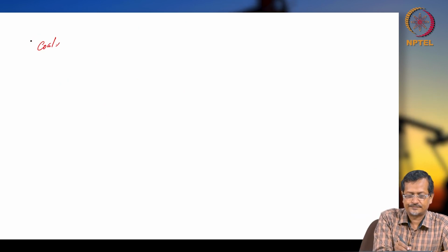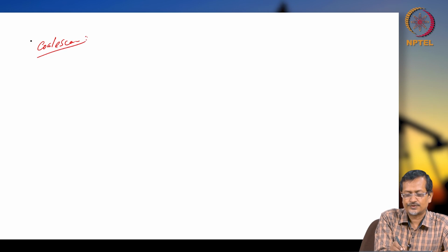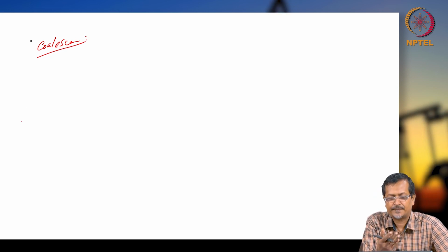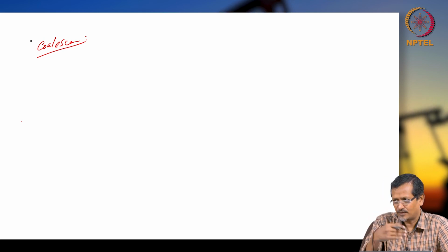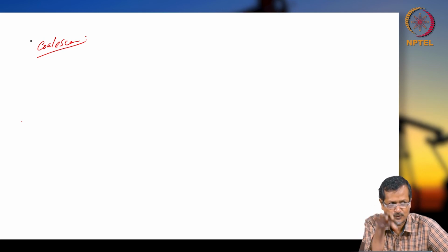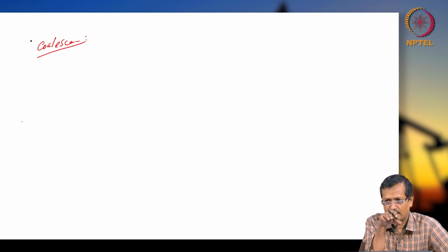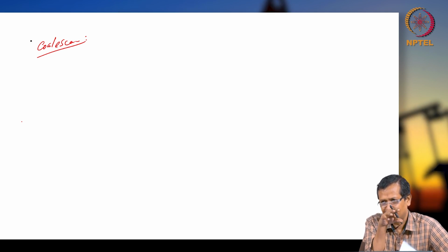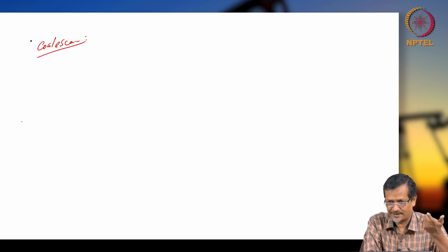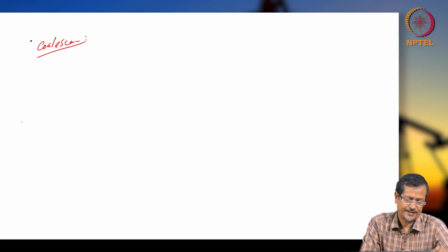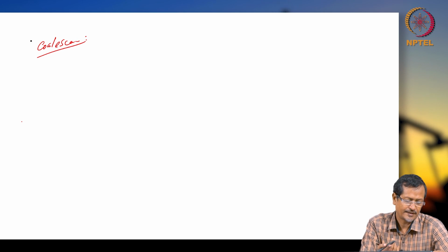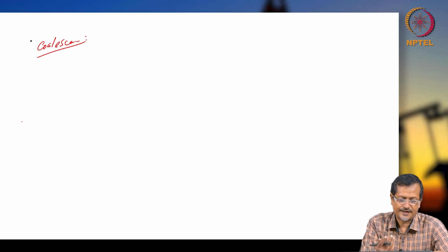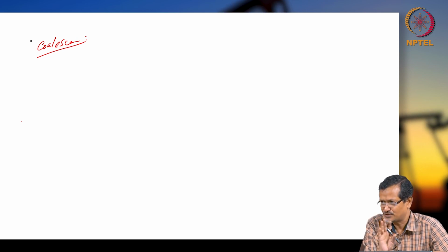Coalescence. So you have seen the VT formula. If two particles are colliding with each other, then the particle settlement rate will be quicker, or the oil particle will settle quickly, so your retention time will be lower. If you want to know retention time Tr, then your particle size should be bigger, so it will be settling quickly. If the droplet pair is exposed to turbulence and fluctuating pressure, then the particle will be smaller in size, so coalescing will be difficult.